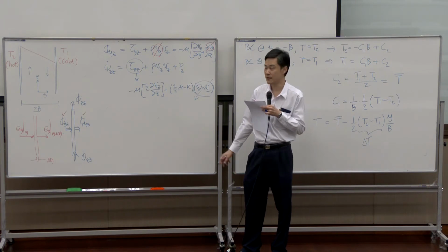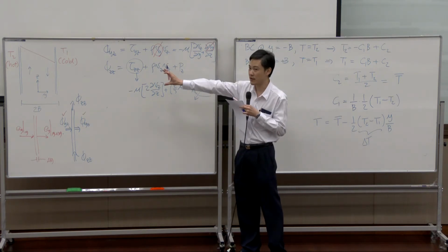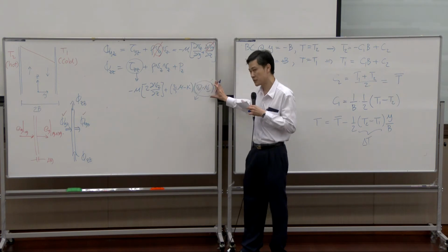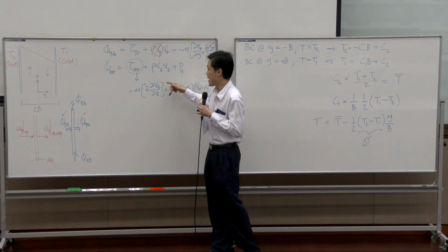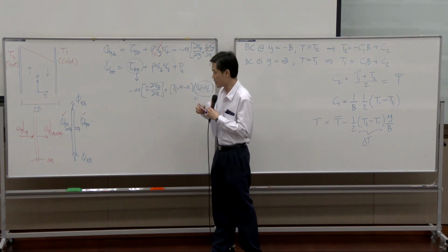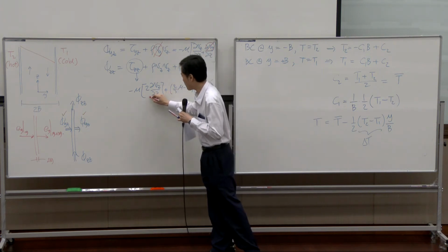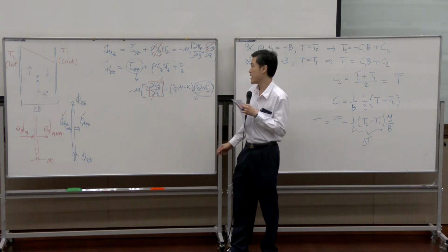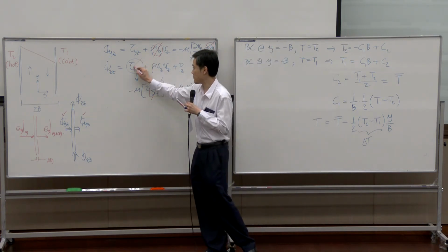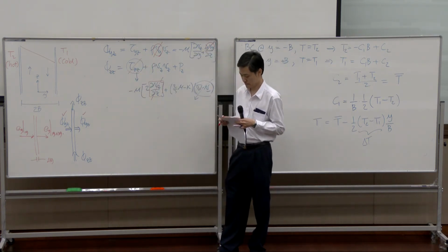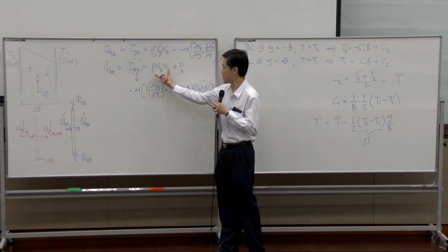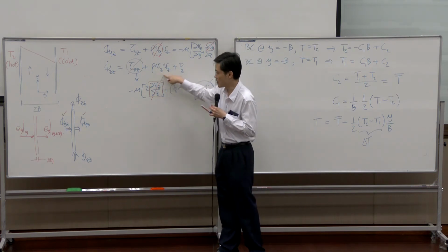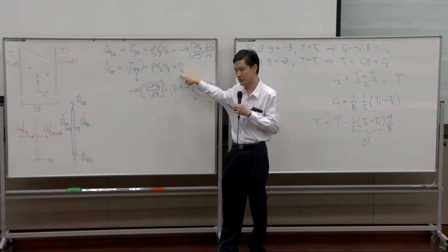Remember, we said every time we have liquid or incompressible fluid, this term will be 0. And Vz itself is not a function of z, it is a function of y. So the whole term turns out to be 0. We only have the convective transport in z direction and pressure.